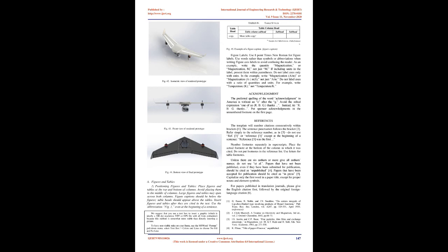H. Static structural analysis. A wing structure consists of multiple layers. The outer layer consists of a hard casing that forms the outer curved section of the wing, while the inner sections contain support structures called spars and ribs. These structures work like iron rods installed within concrete pillars. They provide structural stability and strength to the wing. Failure of these structures can cause failure of the whole wing, therefore performing an analysis on them is necessary.